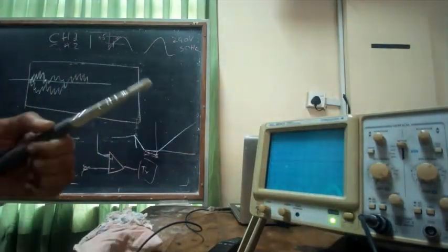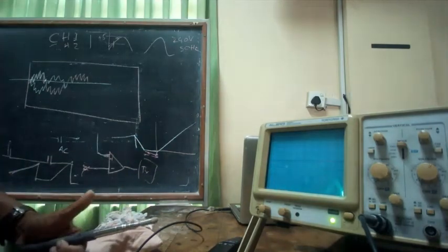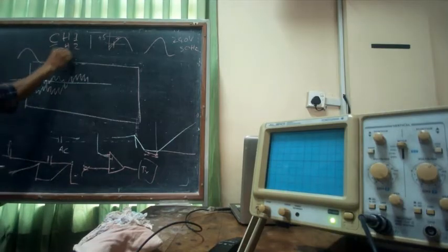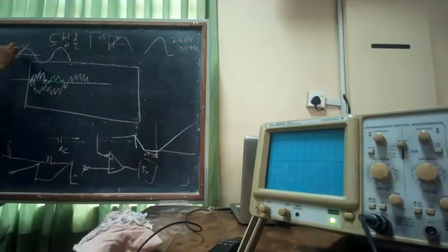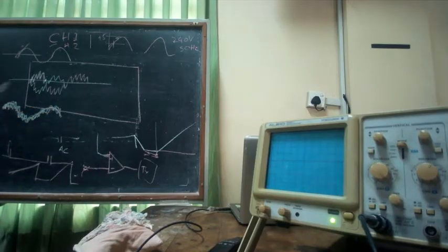If now I have another signal source, a signal generator with 50 hertz or whatever other frequency, I can stabilize this. So you are not waiting until this signal reaches that level. That's the clean signal I am waiting for, so I always start with that. You may have a noisy signal, so you draw something like this. The next time it may be noisy, but it still has the same phase. Next time it has the same phase, noisy. After a while you will see a kind of thick line, just like what you see here.